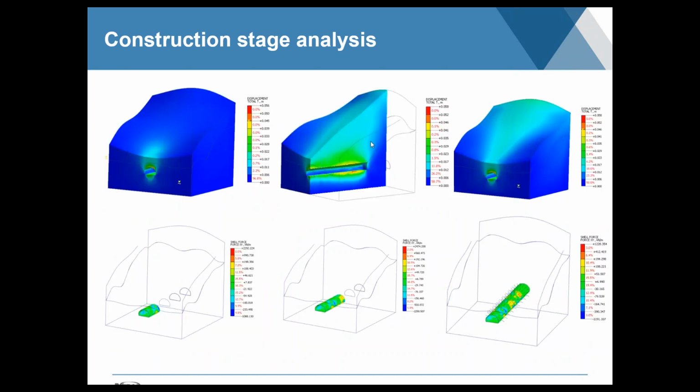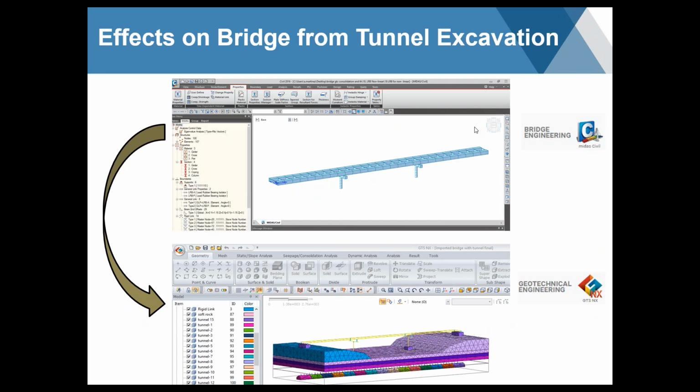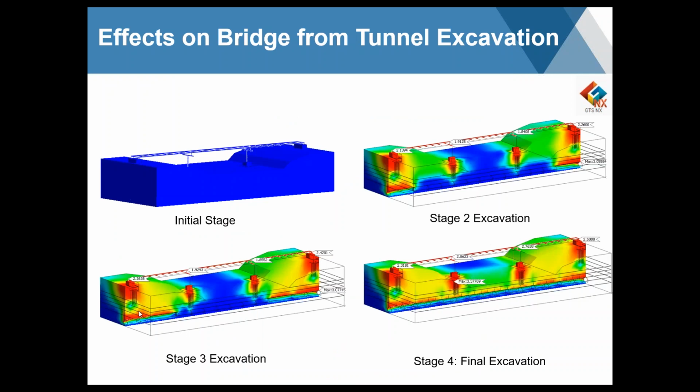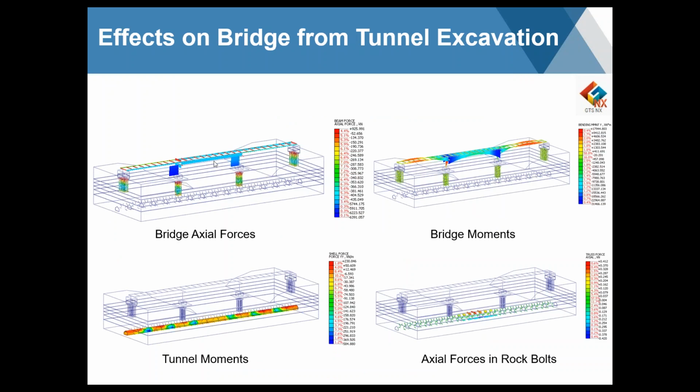Because as you'll see, this same model, if I was to run it even in just 4 excavation stages, the results would look quite different. The concentration is now more about the process of the installation itself of the tunnel, not just a static case of how much potentially it would be affecting the whole slope. And beyond that, with our program, if you have a bridge or structural software, you can import the structure and potentially see how a new tunnel excavation would affect an existing structure. And you can get both results; the bridge team could also be working with the geo team directly and get results for the piles and the structure as well as for the tunnel.